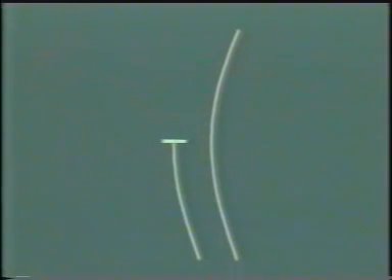This is analogous to the comparison between a pin-ended strut, corresponding to the simply supported beam, and a cantilever strut, corresponding to the cantilever. This correspondence is not exact, as the behavior of beams is more complex, as it also involves torsional effects. The end restraint provided to a beam has a major influence on the occurrence of instability and can be utilized to enhance the load carrying capacity whenever instability is likely to occur.